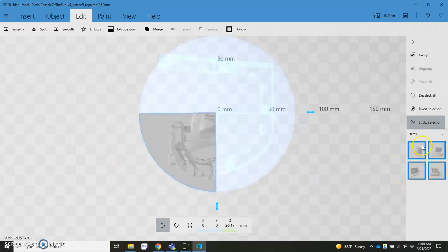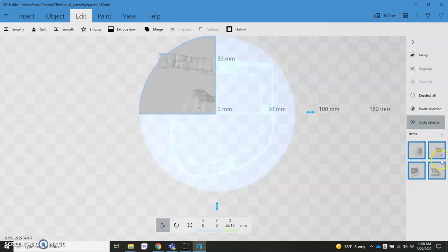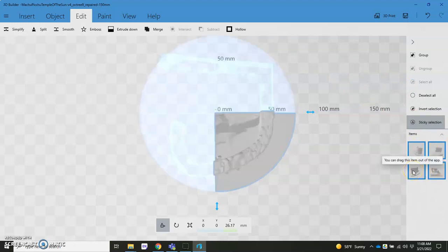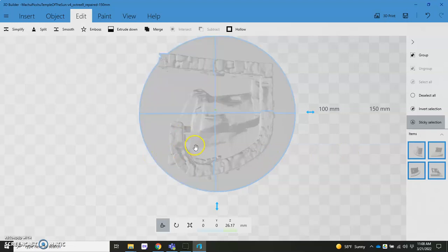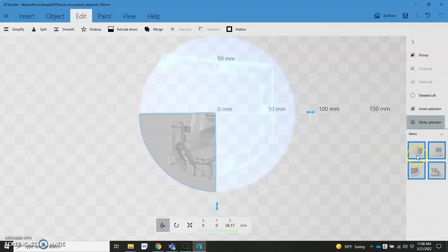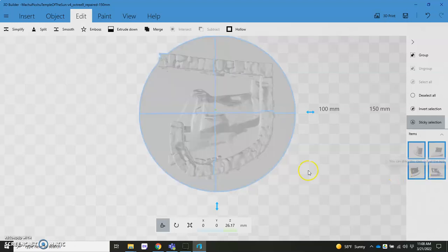So now when I go to my printer, I'll print this at max capacity, or at least, as far as it can fill up the bed, and then I'll print all of the other ones at the same scale change so that they'll fit together and be a much larger print. So what I mean by that is, if I put this in my slicing software like Cura, and I tell it to increase scale by 30% or 100%, I need to make sure that same percent increase on the scale is being done for each of these models before they're printed, right?